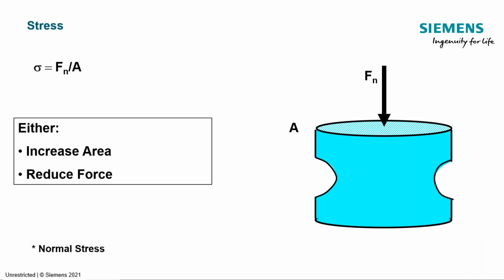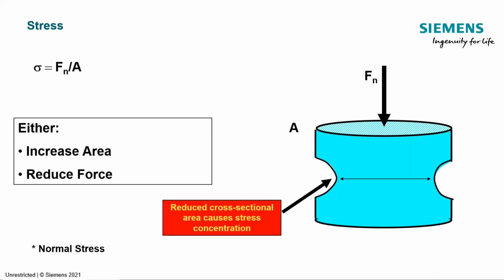Now, whenever we change the geometry, we need to check the stress. And our CAE friends, colleagues, should be doing this. If we make geometrical changes, we should check stress distributions. Because sometimes people have to do things like packaging, so they have to change the geometry to make this all fit. Whenever you change the geometry, you should take a look at the stress. It has a big effect.